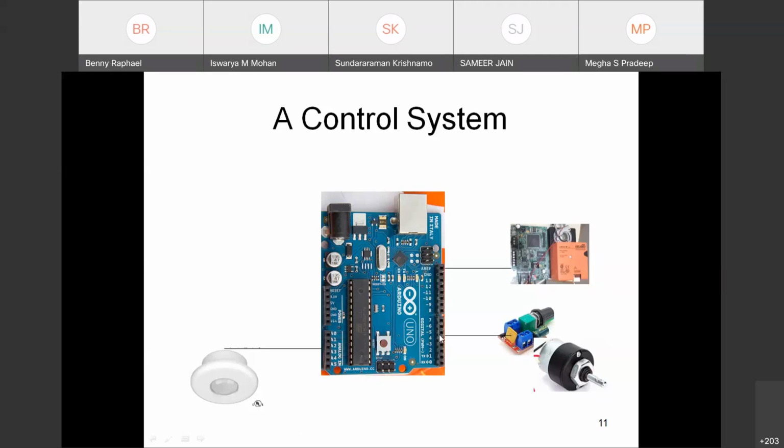So here we have the controller, which is the equivalent of the brain. And you have sensors which are connected to it. We have the input channels to which we connect the sensors, and these sensors typically produce either a voltage or a current. This is how we communicate today using electronics. So the sensor might produce a voltage in the range 0 to 5 or 0 to 10. And this controller is able to read exactly what the voltage is at each of these pins.